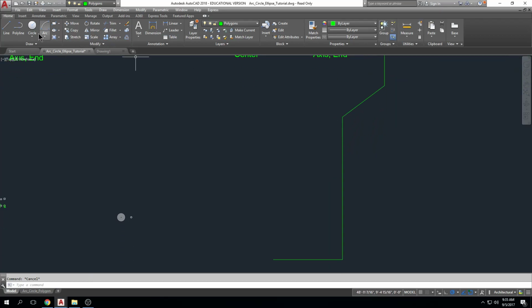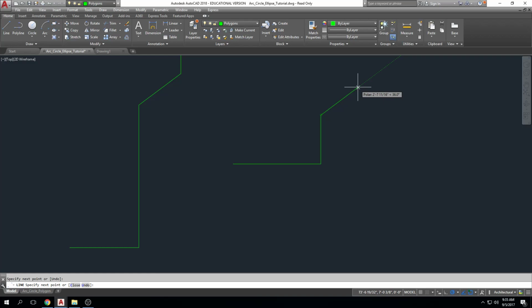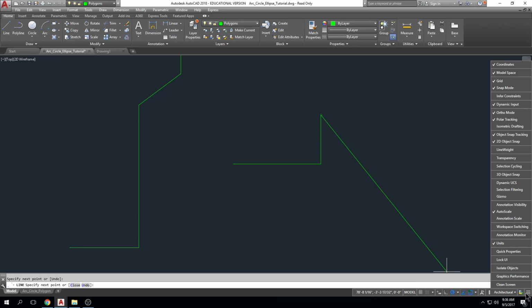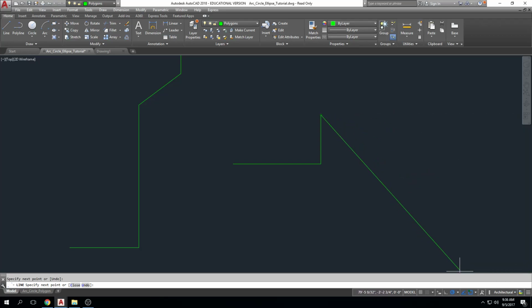Yeah, yeah. Okay, so I'm cruising along here with my direct input. Click, I'm typing in dimensions, and now I need an angle, and maybe my angle's 135. So I can come down here to my polar tracking. If the polar tracking isn't showing up, it's this little icon right here, then you'll come over to these 3 little lines and make sure that polar tracking is turned on. Then I would look and see if the angle that I want is listed. Okay, well, 45, 90, 135, there we go. So we've got 0, we've got 45. See how it's telling me off to the right? So I can come down here and snap.